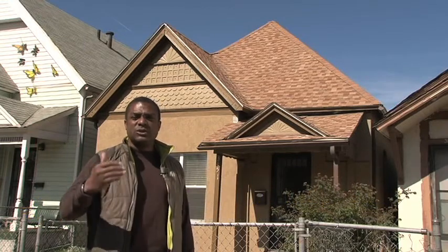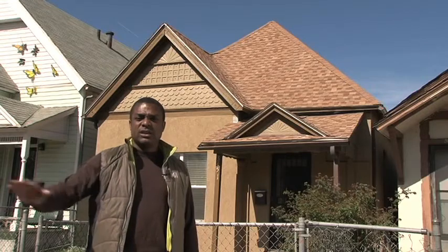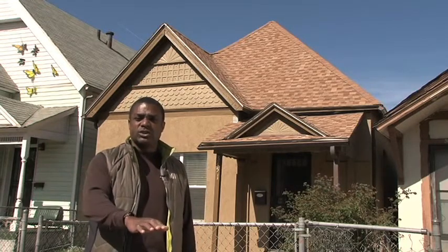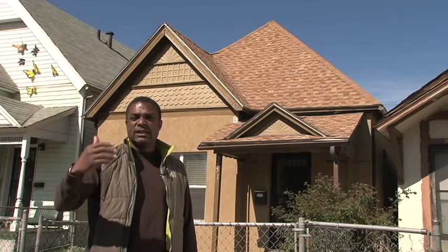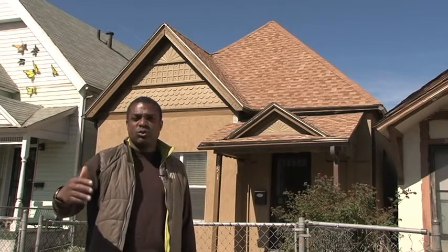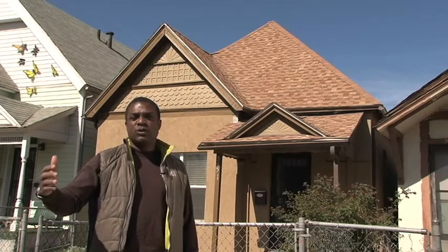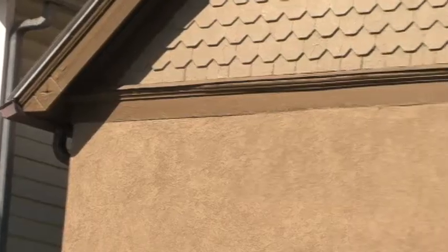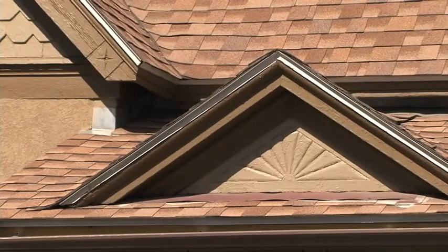As you walk up to the house, you'll be looking at the drainage from the house. Is the dirt sloped away from the house to give us nice, good drainage? When we get up on the porch, we're going to take a careful look at the siding and the condition of the door. After we take care of the paperwork with our homeowner, then we're going to start our walk-around section. As we're doing our walk-around part of our inspection, we want to be pulling our dimensions and making our drawings and making our notes.